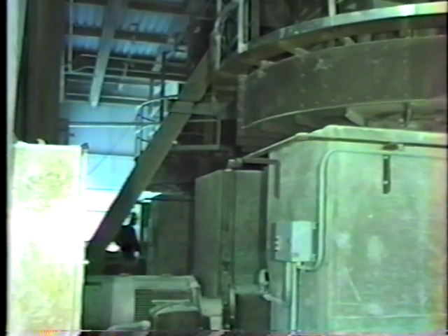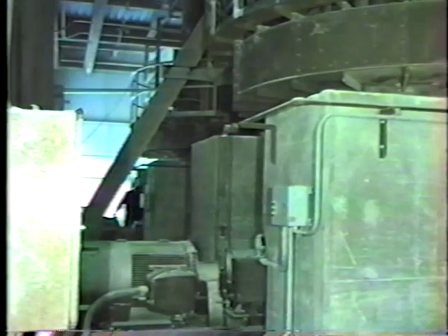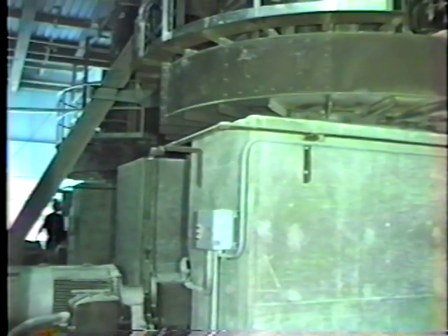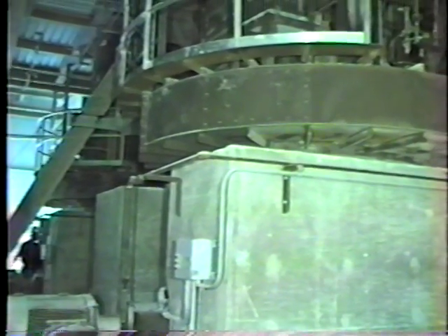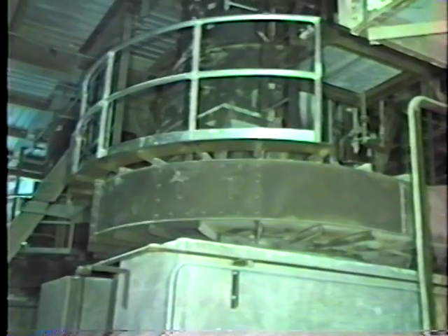The hot gases are conveyed to circular bustles, which we call wind boxes. These wind boxes surround each pulverizer, and they introduce air equally around the periphery so as to fluidize the coal and dry it, and convey it up to the active classifier we call a spinner separator.